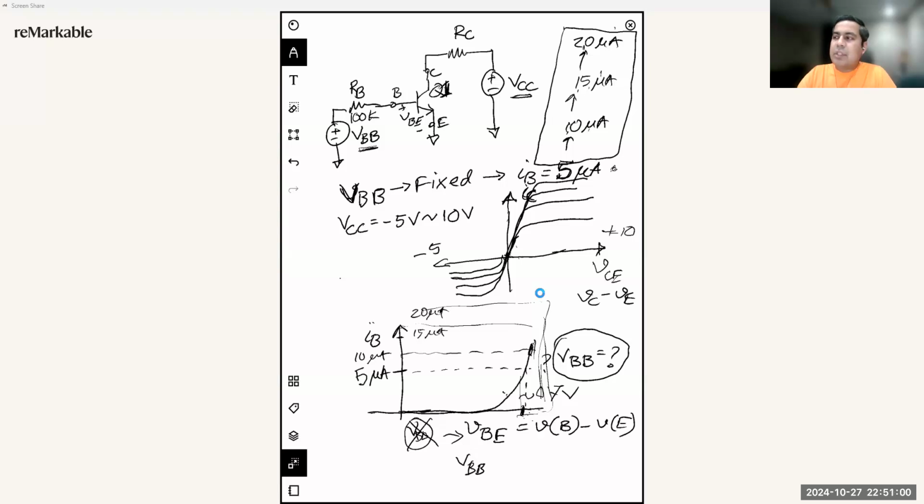Once you are done with the simulation, we can move on to do it again in the experiment. You build this circuit using this BJT part. The part number is also 2N3904. It should be in your lab kit. I don't exactly remember the part number. If the BJT chip in your lab kit is different, you can still get this 2N3904 chip from the parts store.